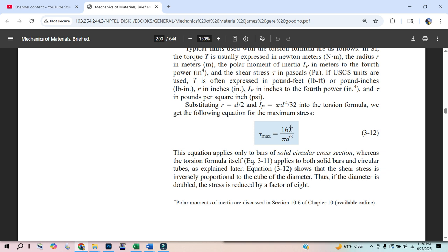So if this is T, we're going to get pi upstairs. So we got pi times T max, we already said that, times radius to the third divided by 4. So this is going to be pi T max d to the third divided by 2. We want to divide by 2. And so we're going to get pi times T max times d cubed divided by 16 is torque. You know what I mean? That's where it's just like these textbooks, they should show you at least like 4 different ways that say the same thing, because they make too large of jumps.